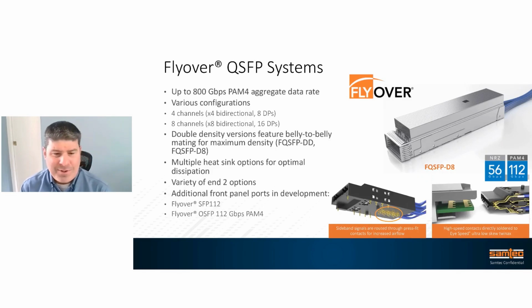To achieve the best results for routing data within AI system architectures in the data center, typically you take the signal out of the PCB and put it into an ultra-low skew twin-ax cable to route the data over longer distances. Why do we do that? In general, twin-ax cable has about 1/3 the loss of PCB materials, even advanced solutions. So Samtec offers the widest variety of cabled interconnect in the industry.